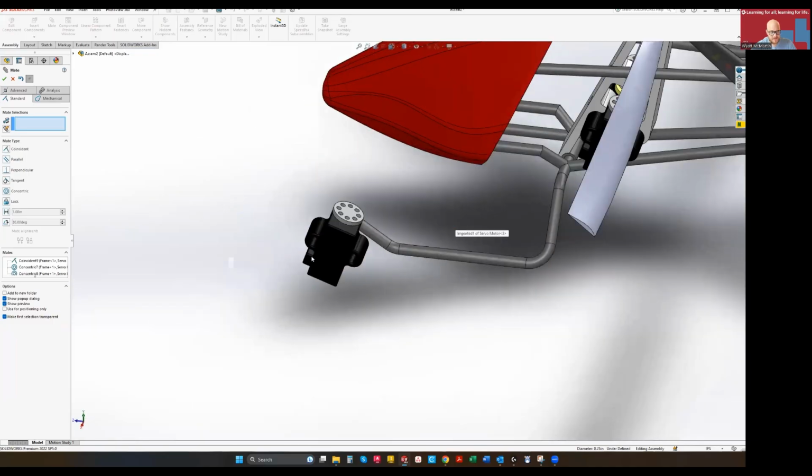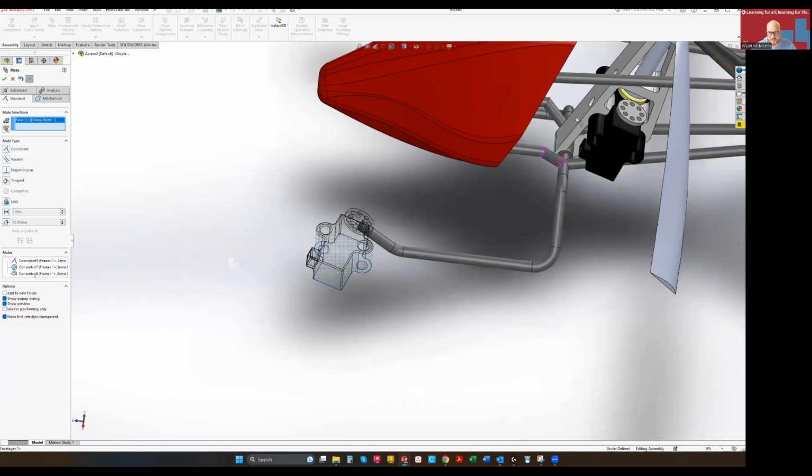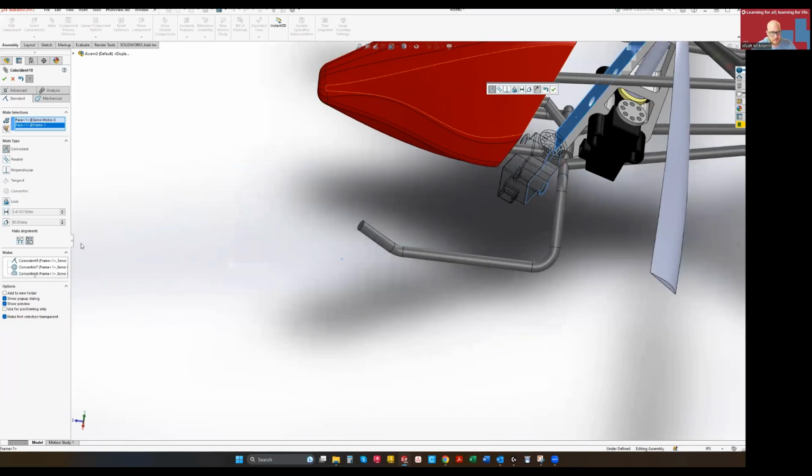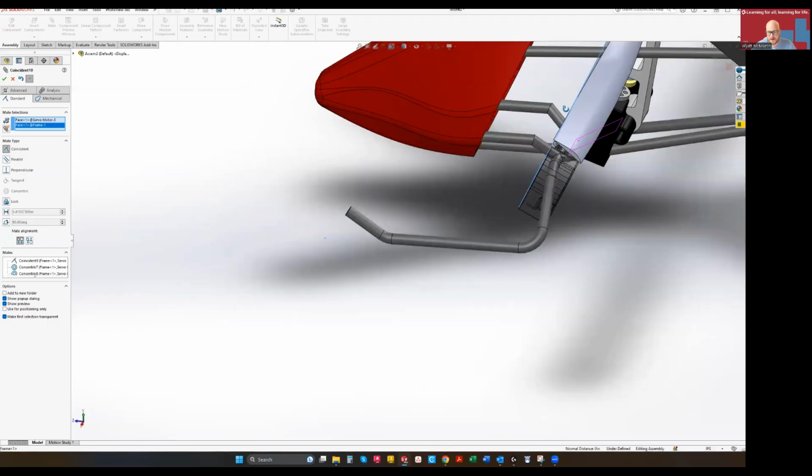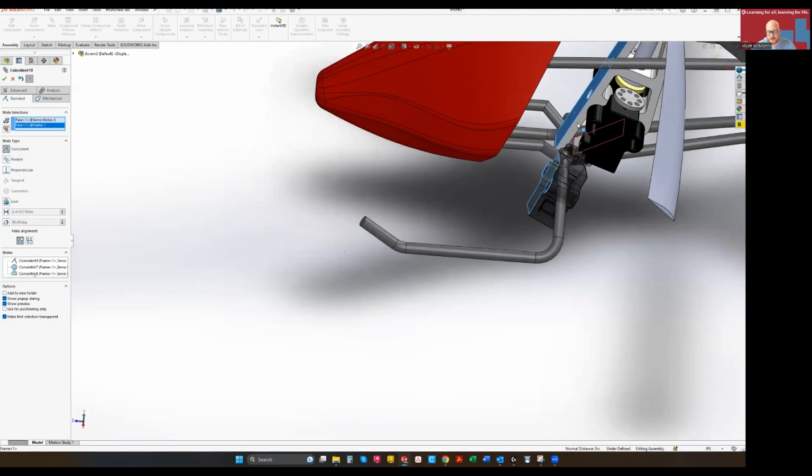Usually, until now, I've had you rotate the part when it isn't already set up the way I want you to mate it. But instead of rotating the part this time, let's just click that face and click that face. Okay, so it did rotate this around properly, but sometimes it'll be the opposite direction of the way you want it. So obviously this isn't going to work because this would be inside this piece. They would be conflicting. So there's this mate alignment button.